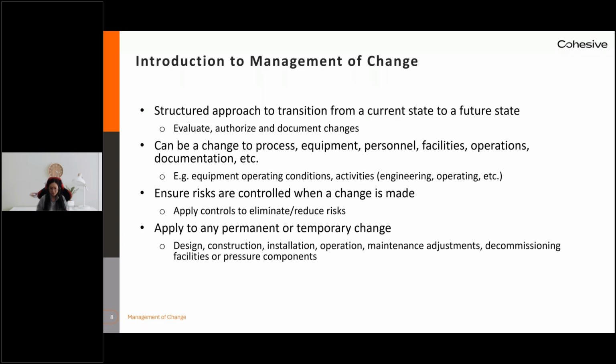Your procedure should also encompass technical information, potential impacts of the change, including risk assessments. Management of changes should also include proper authorization, either through a review process, a change approval board, or an authorization procedure. MOCs should also assign personnel to approve or handle various tasks related to the MOC. Additionally, you should also have a process to track your action items.